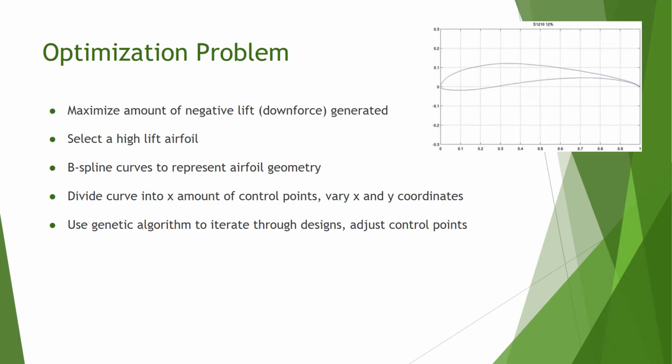These curves will be divided into a certain number of control points which have explicit X and Y coordinates that can be adjusted based off of the CFD simulation force results. The plan is to use a genetic algorithm to drive the iteration of designs, making adjustments of the control points until an optimal solution is reached.